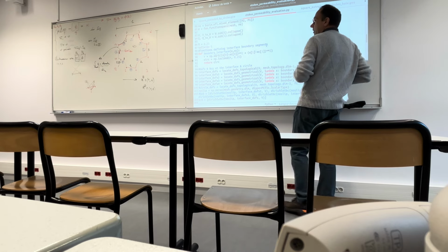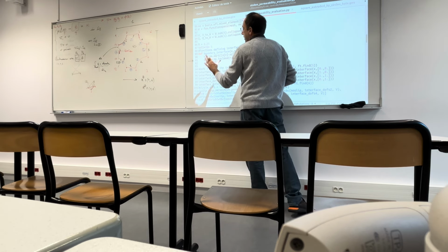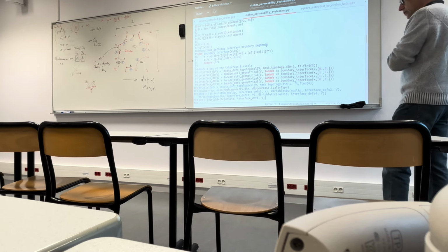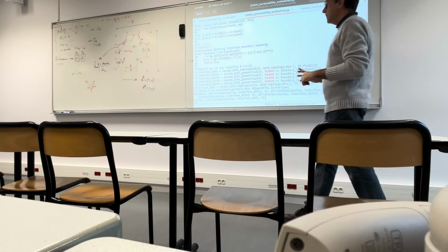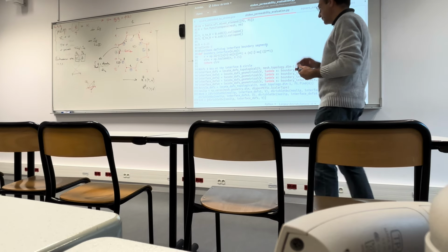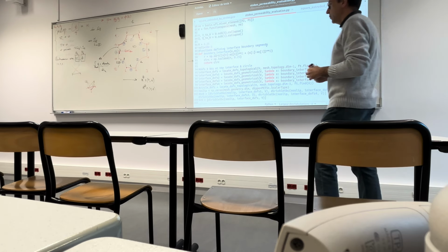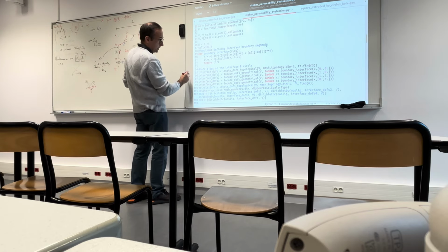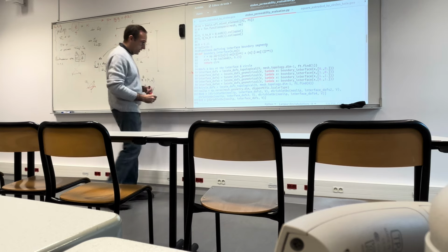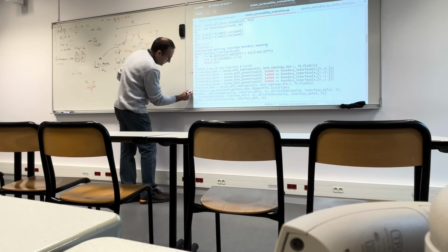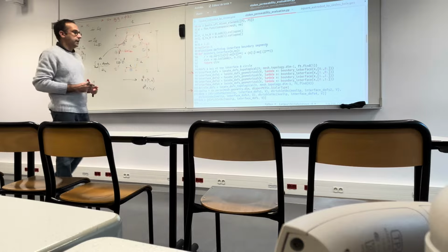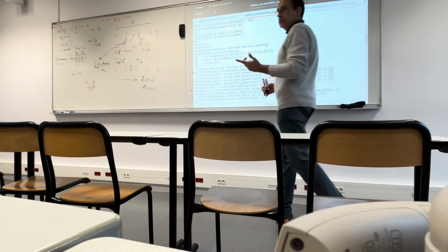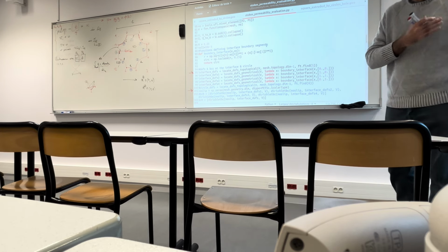And so in this way, we have identified the degree of freedom for the velocity for which we want to assign 0 boundary condition. So this would be sufficient to assign 0 velocity. Consider line 95. Then there is line 101, which just introduces a vector of zeros, because we want to assign 0 velocity.